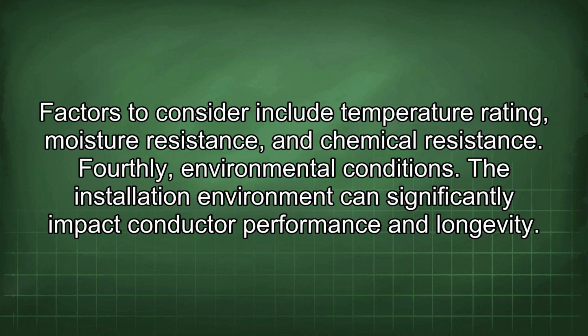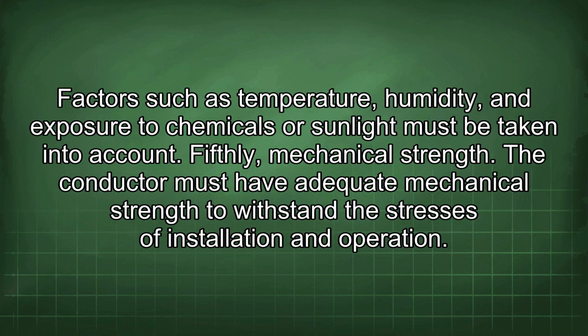Factors to consider include temperature rating, moisture resistance, and chemical resistance. Fourthly, environmental conditions. The installation environment can significantly impact conductor performance and longevity. Factors such as temperature, humidity, and exposure to chemicals or sunlight must be taken into account. Fifthly, mechanical strength. The conductor must have adequate mechanical strength to withstand the stresses of installation and operation.